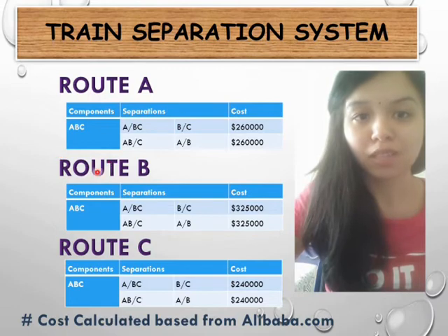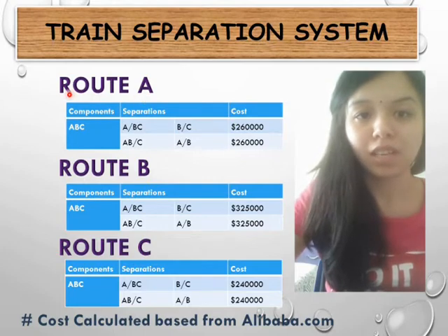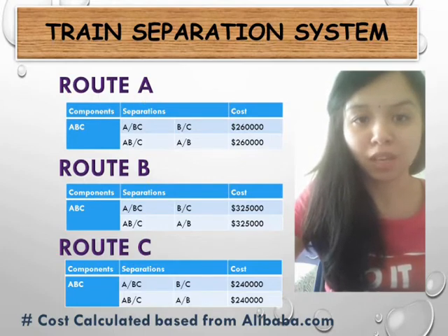Three components are to be separated in all the three processes. So, two separators are required to separate three components. In route A, which is acetylene co-product process, the three components to be separated are C3-acetylene, 1,2-butadiene and 1,3-butadiene.